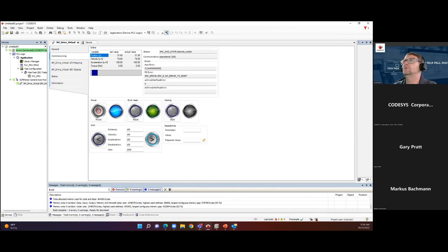Now as I start to move, you can tell that I'm actually moving the axes. I can actually see that I've moved. If you did not catch that, when I was holding the button down the whole time, it was moving exactly 100 counts, or 100 units. If I hit it again, it'll go up to another 100. So I'm at 211.64.